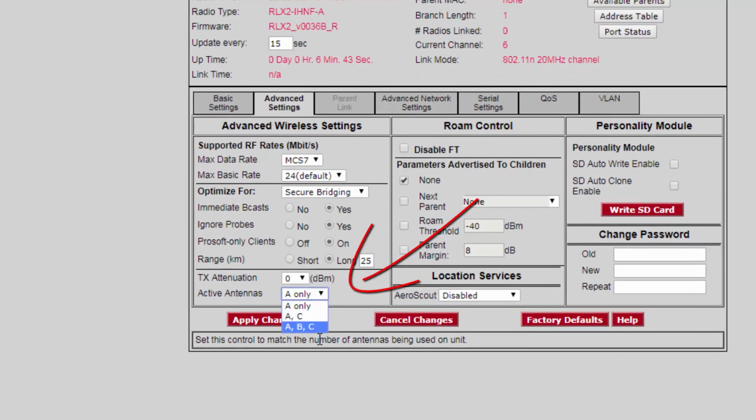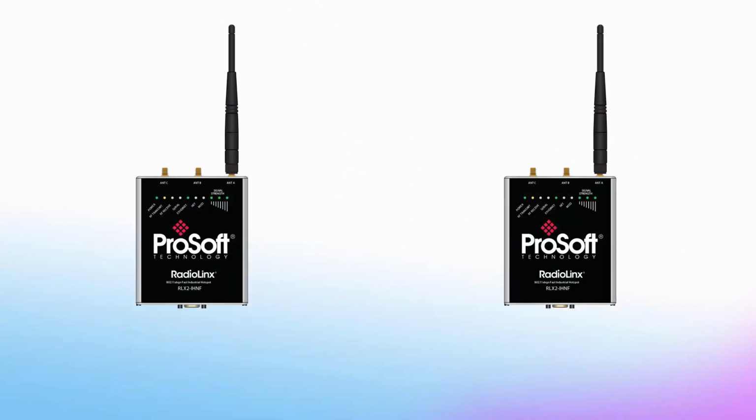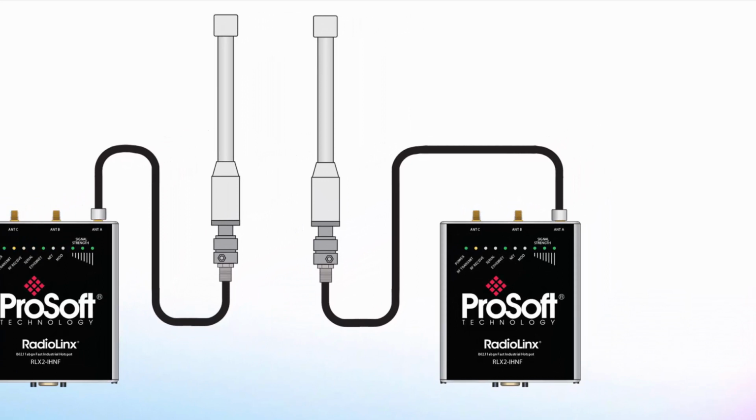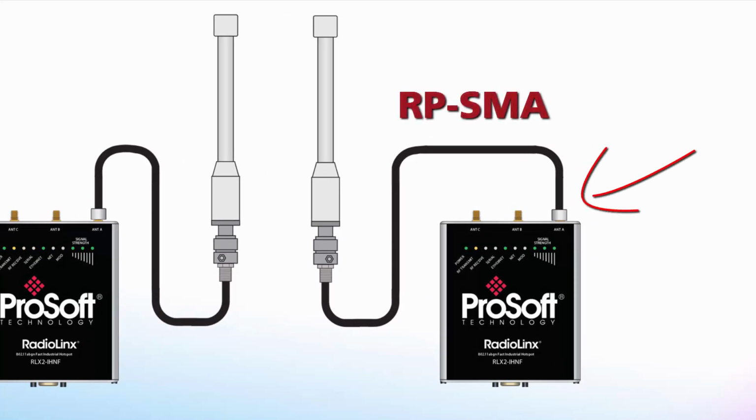As a side note, if you're doing a bench test of your radios, you can simply use the articulated antennas that come with the product. But if you plan on using a mounted antenna when you deploy the radios, you must be sure that you're using the proper conversion cable to connect to the antenna. For our RLX line, this is a cable with an RP SMA connection for the radio.